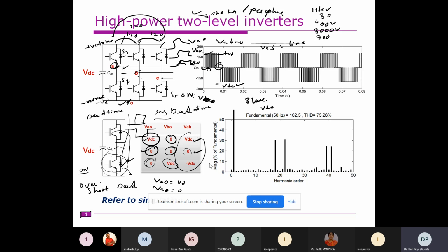But because I have been working on multi-level inverters for the past 6 years, from my knowledge, if you strictly ask me why we have to go for a number of levels, it's only depending upon the desired rating. That's how it is designed. They will take the overall output requirement with respect to the DC requirement, with respect to the switch voltage requirement. For that, what is the available voltage, then the available device, then they will take multiple modules and do it.